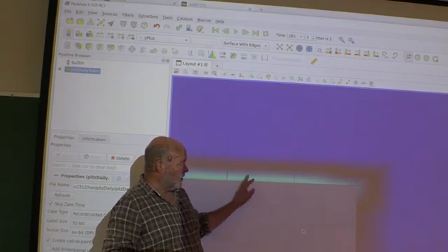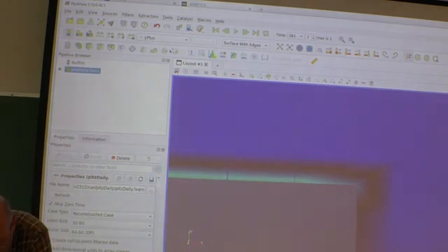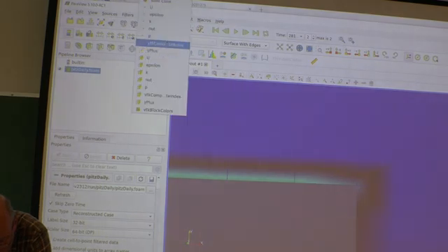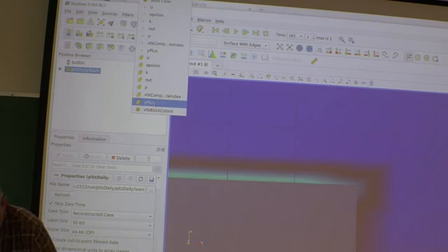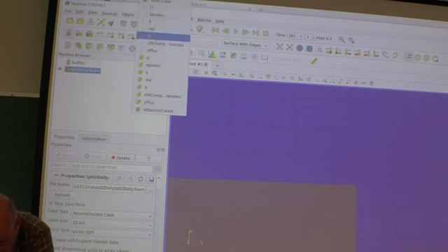So it's the wall value that is important. If you use the other y plus here, not the interpolated one, it will give you a constant value for each cell. Well, then you don't see anything. So you have to use this interpolated value here.